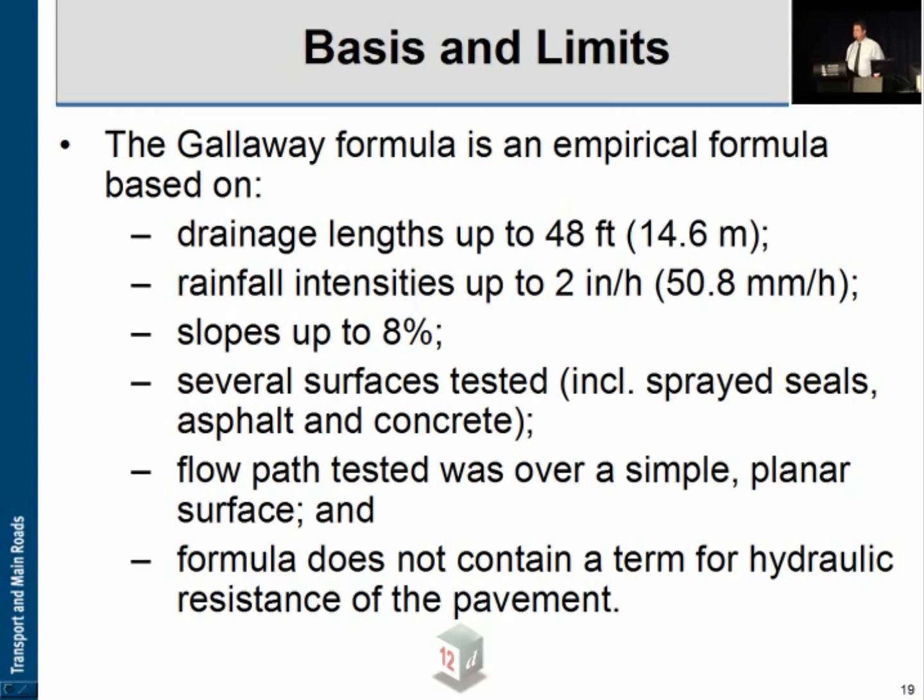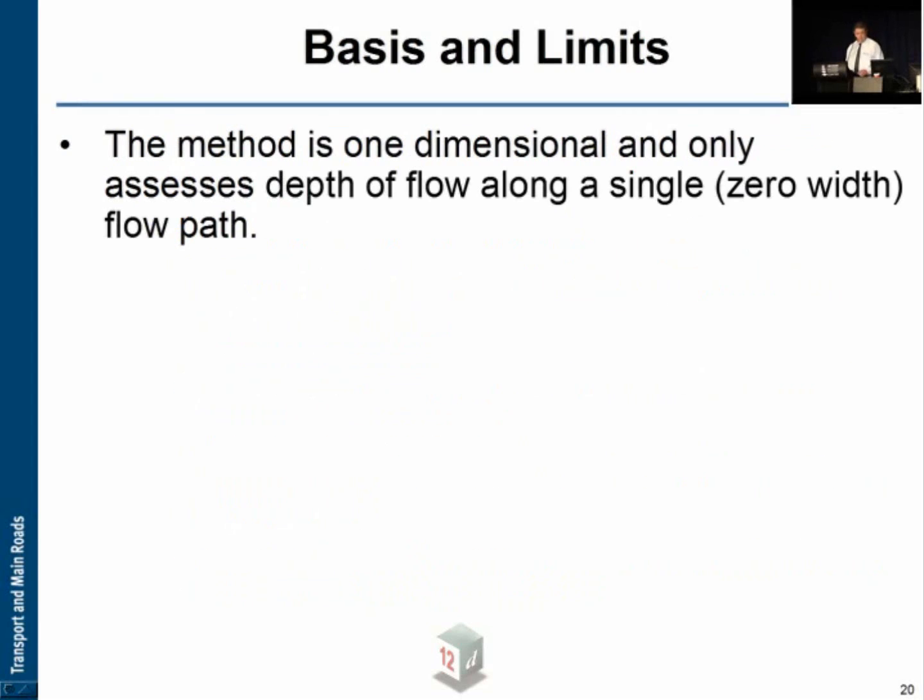And some of the criticisms of the formula is it doesn't contain a term for hydraulic resistance. There's no Manning's n or Horton's n or something like that in the equation. However, because it's an empirical equation, that resistance is sort of built in, and the texture depth is possibly not directly related, but a way of allowing for it.